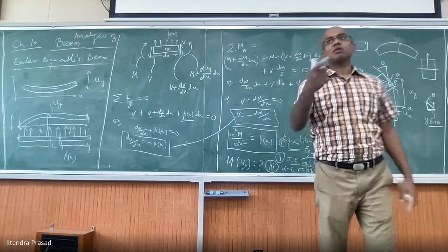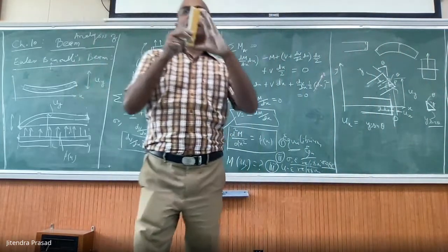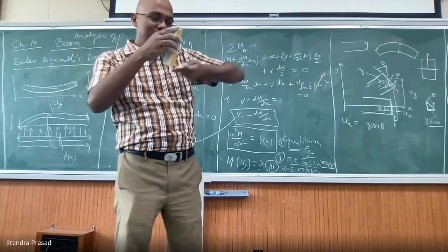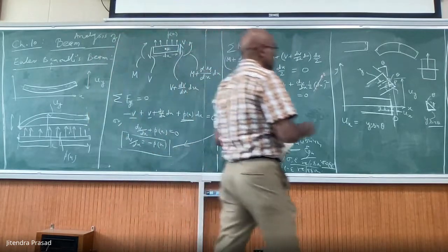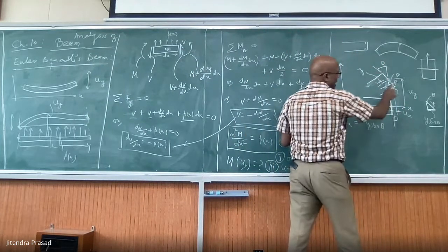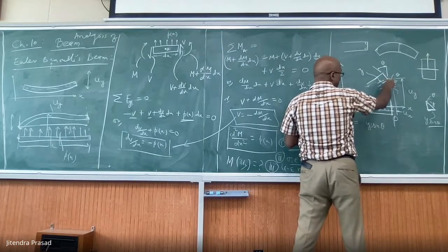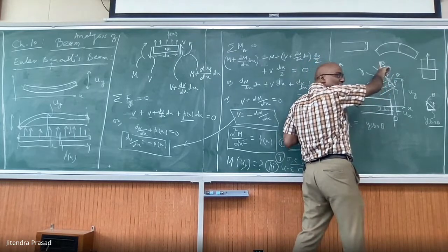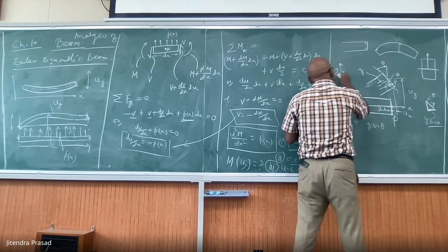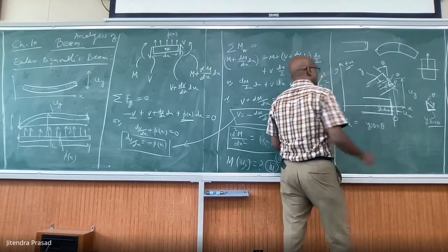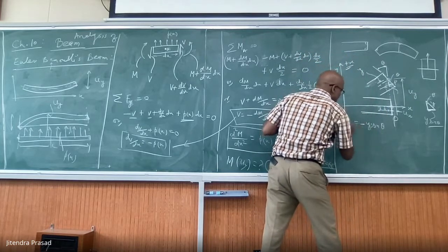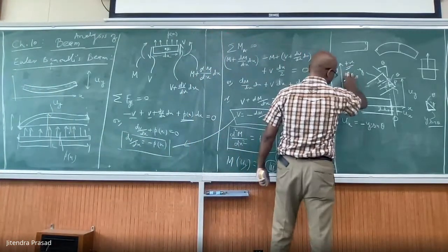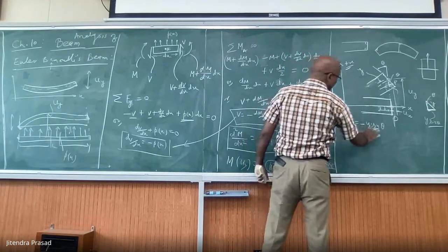Anyway, theta is very small, so if some distance here is theta, the component of that will be y cos theta here, y sin theta. We are talking about the component of that. Another thing you notice is that if y is negative, x is positive. Here displacement will be negative, here displacement will be positive, and our y is positive upward. So basically, we need to say Ux is minus y sin theta. Our convention is y positive upward.